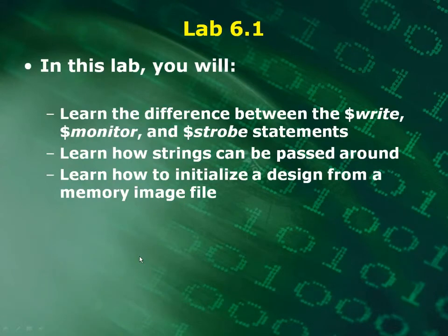In Lab 6.1, I want you to learn the difference between the $write, the $monitor, and the $strobe statements, and learn how strings can be passed around, and learn how to initialize a design from a memory image file like we were doing.